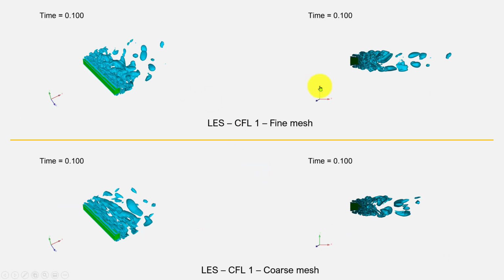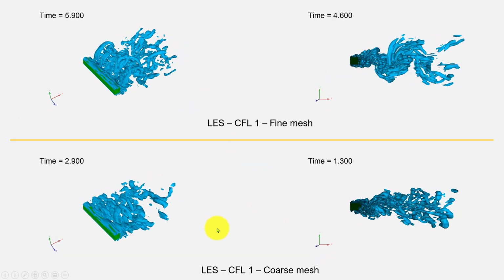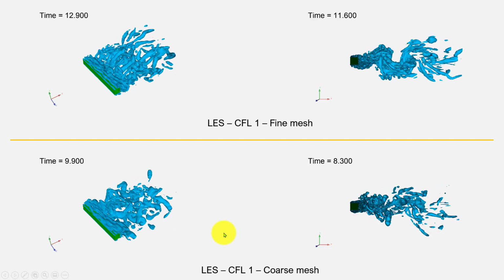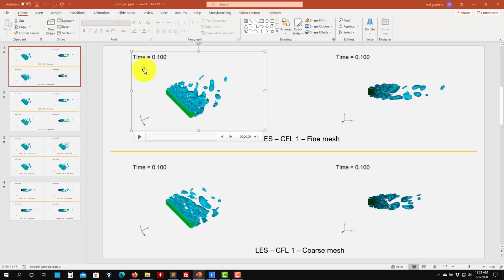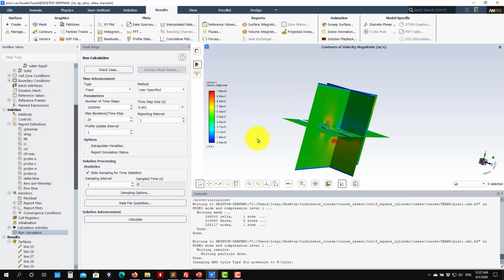So let me show you all. You have all here, okay? And we're going to save the solution as well to do some post-processing. I will show you how to do that. So now our goal is to choose a time step. Remember, ideally CFL of 1 will guarantee good accuracy. But if you have a CFL larger than 1, it's also possible, you advance faster, but you might lose some information in your solution. So here we need to choose that one, and that is the tricky part.